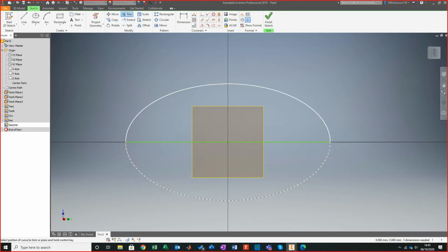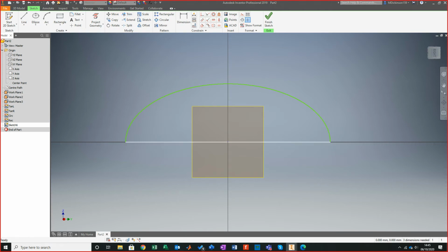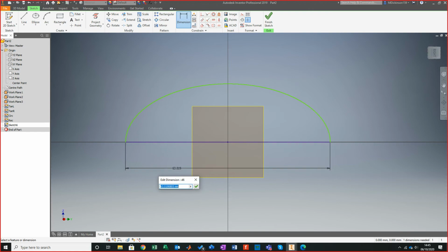I'm going to trim that out. And yeah, it's still. I mean, if I pull that down, that's really annoying. Might be because of some of the turn-offs that I did. So I'm going to just add that midpoint on again, like that. It's not too much of an issue. And what I'll do is do a dimension from there. This is now 100 millimeters.